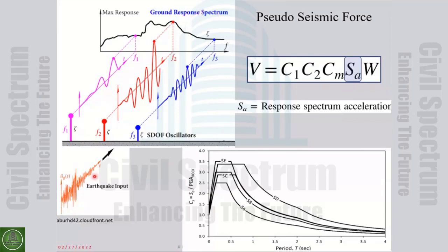It's not the ground motion spectrum, but it's the response of the building to that ground motion. Very nice tool. So if we have the period of the building and they provide us, either from code or by site-specific study, the response spectrum for that level of the earthquake,